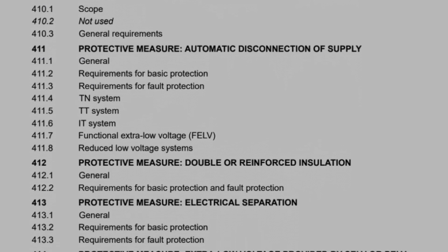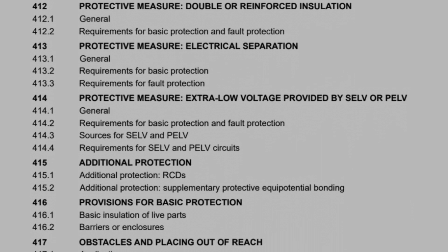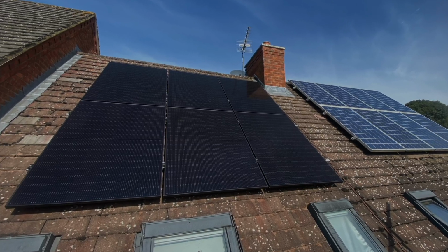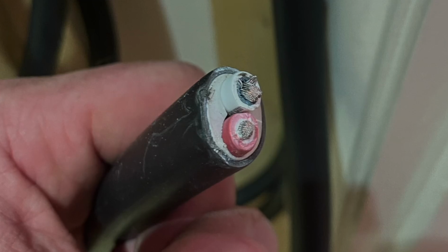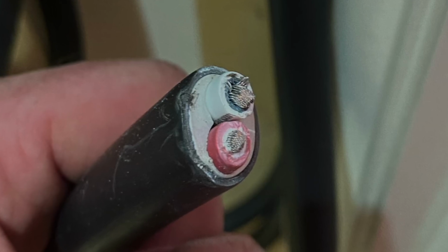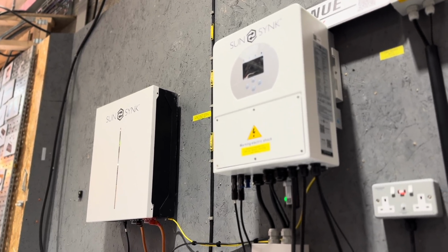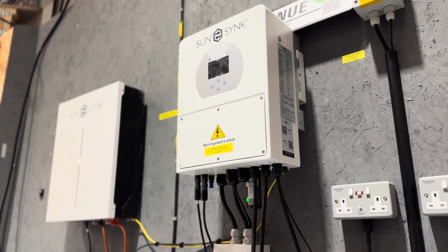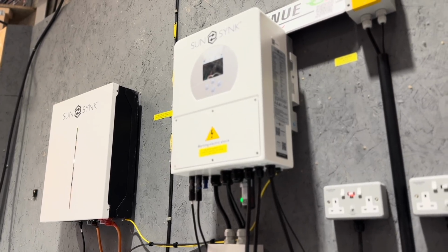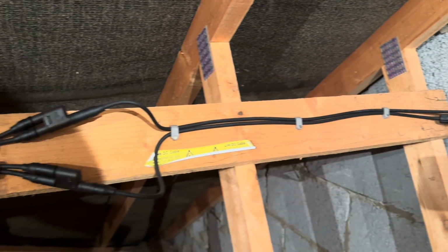But the DC side from the PV array and the batteries can create fault currents, and this needs to be accounted for. Solar panels can short circuit. This is perhaps when the positive and negative conductors have inadvertently come into contact with each other. However, protection for this is not necessarily a requirement on the installation. But why is this? This is because manufacturers install insulation monitoring devices which monitor the PV array, and if a breakdown in insulation was detected, the inverter can isolate the panels automatically and send an alert message to the owner and installer.